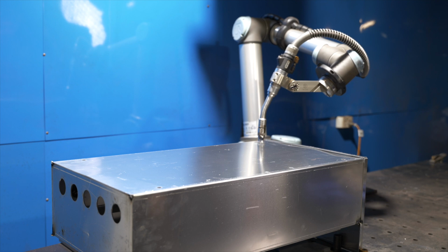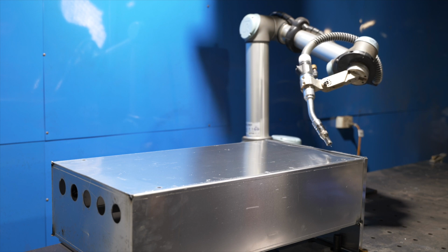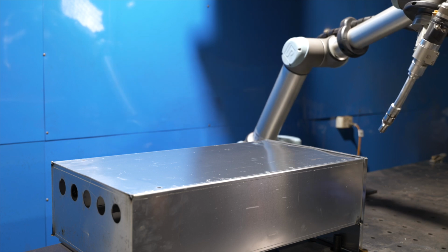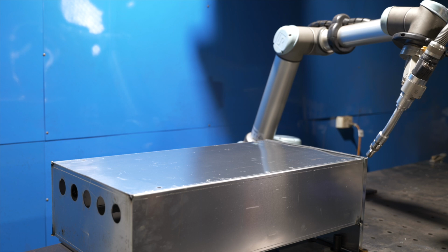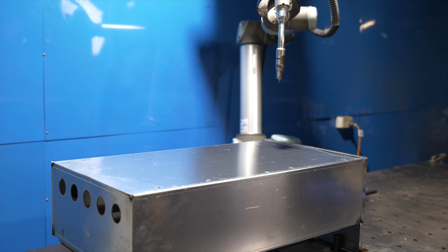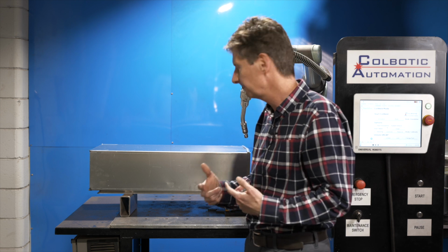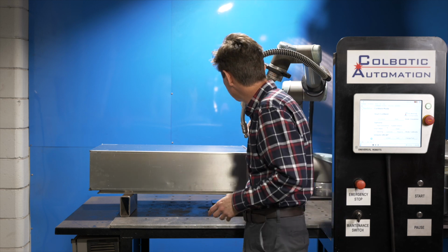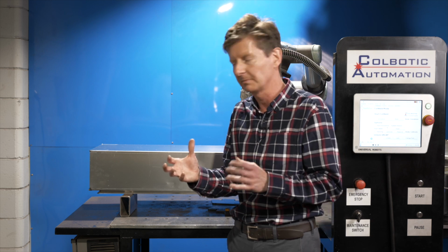So you can see that it's now measured those 4 points. It will then go and do the weld, and of course this weld goes exactly where you did the original program. Now, once it's run through for the first time, it stops. You then stop the program, and it automatically transfers to measuring mode. Okay? So what happens there is the next time you run it, it's actually measuring those same points, and then this weld is changed according to the new position.